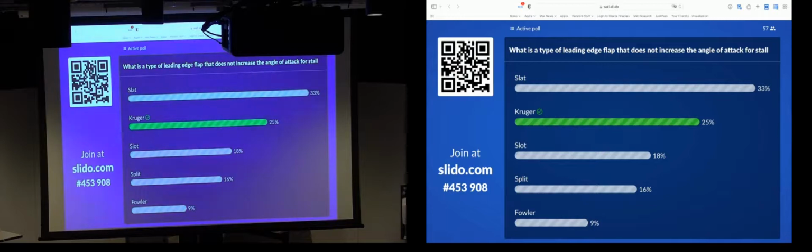Now that reduces the distance from the neutral point to our CG. It reduces our static margin. That means as we go up an angle of attack, it reduces the amount of force it takes to increase the angle of attack further. It also means the aircraft may not stall cleanly, it may just mush. So it doesn't pitch down when it stalls, because the inner wing hasn't stalled, which is a problem.